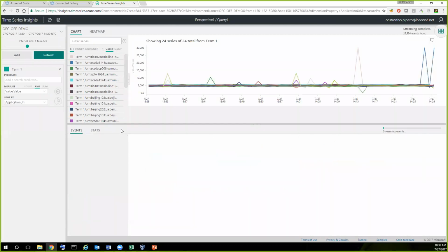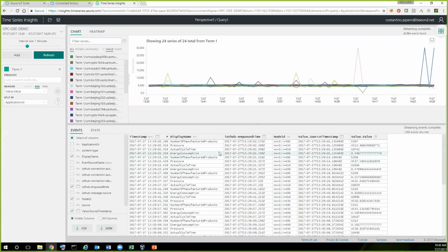So in order for me to have that, I have to create tags, or nodes or items that actually have that calculation in it. So this is a key difference. You can do this because OPC UA allows you to model information, not only to display tags, registries, MQTT points. It's also taking those and aggregating that. And then only the aggregated information will travel across to the cloud to feed the system that needs it.